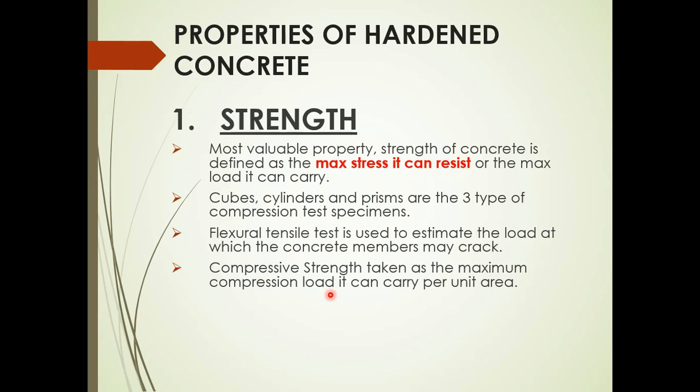In this test, we estimate the load which the concrete can carry before it cracks. This means when we apply load, it deforms and we check the cracking. We also check the compressive strength, which is the maximum compressive load the concrete can carry within a unit area.